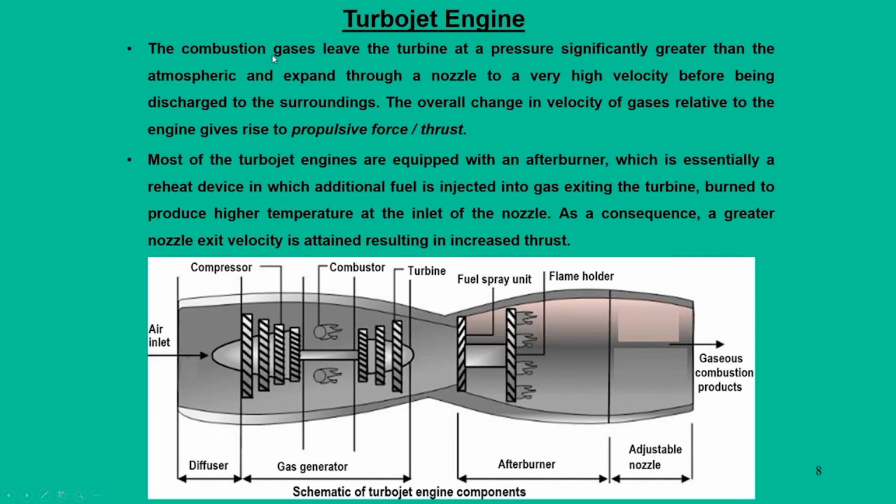So, the combustion products leave the turbine at a pressure significantly greater than atmospheric and expand in the nozzle to a very high velocity before being discharged to the surroundings. So, the overall change in the velocity relative to the engine gives rise to the propulsive force or thrust. This rate of change of velocity, when multiplied by the mass of the system, gives the necessary thrust, and we call this the propulsive force or thrust.